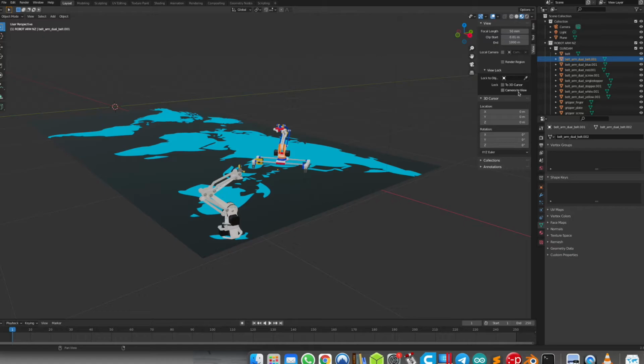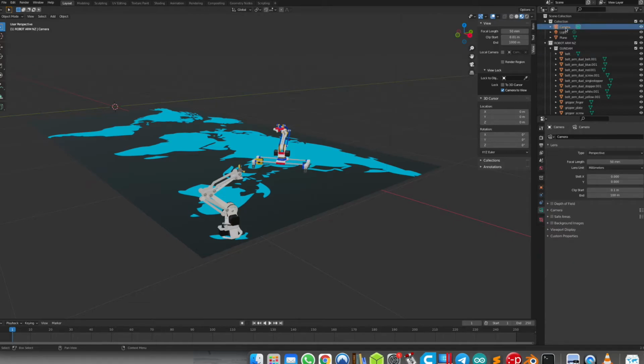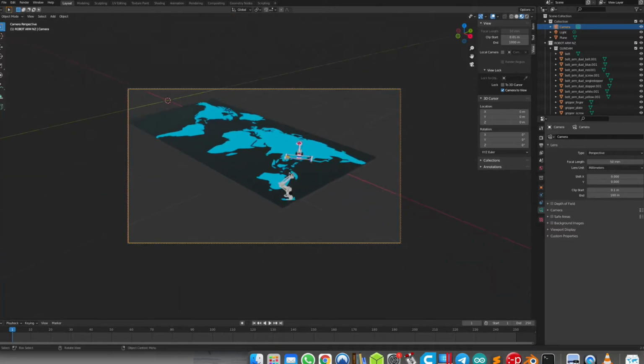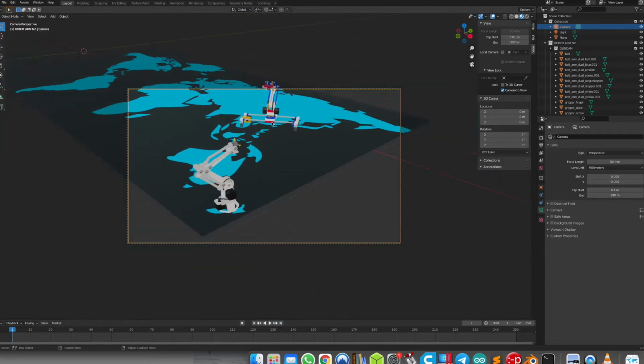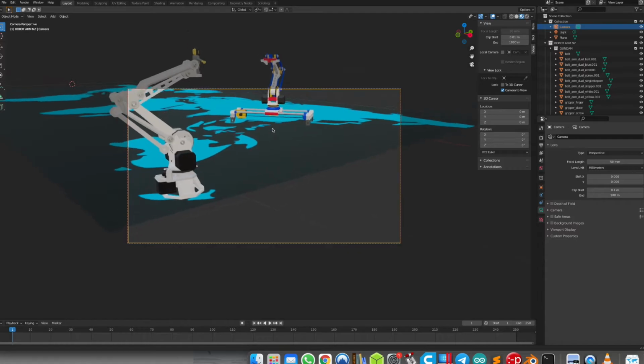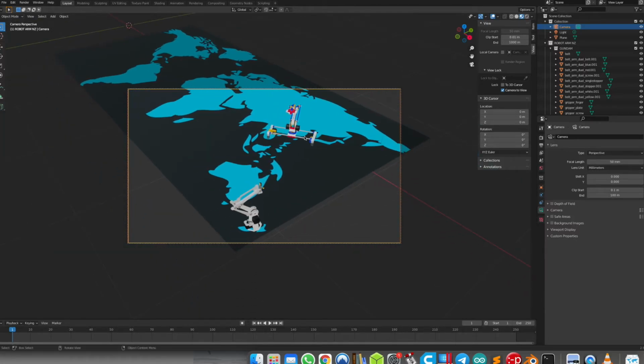In the list on the top right of your screen, find Camera, highlight it. We can play with the settings later on. We can press 0 on your number pad to snap the viewpoint in the perspective of the camera. Because in the checkbox we locked Camera to View, we can now zoom around the screen in the perspective of the camera.